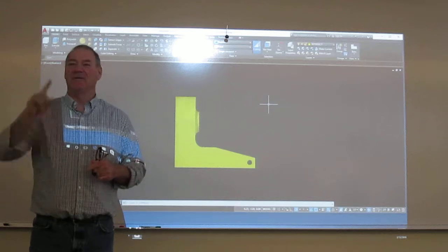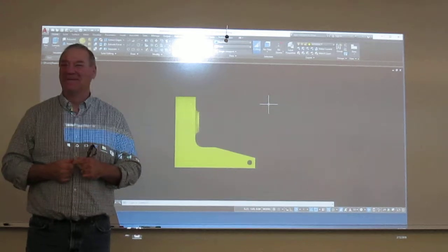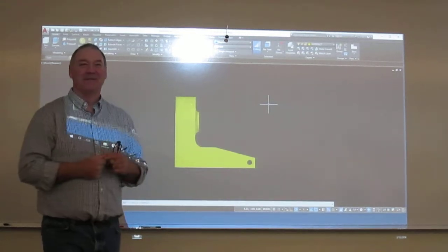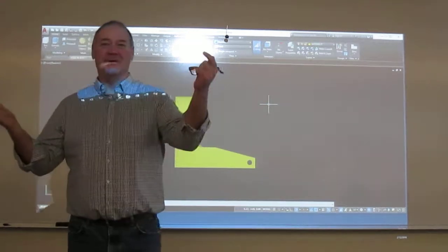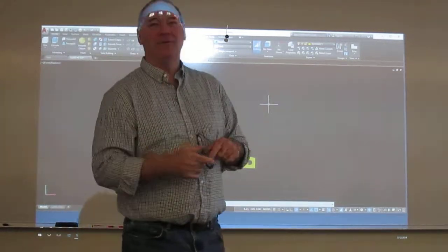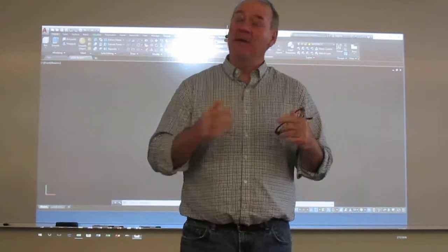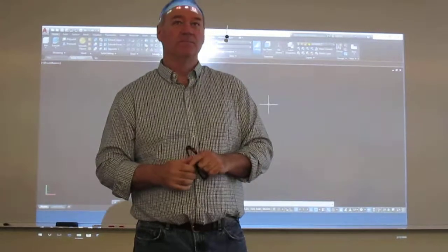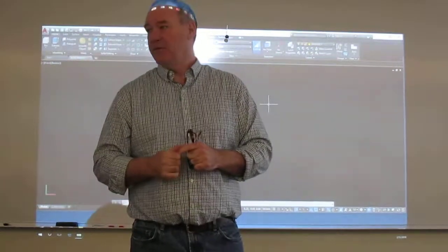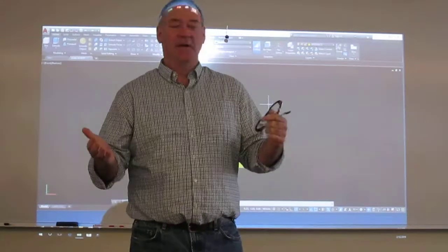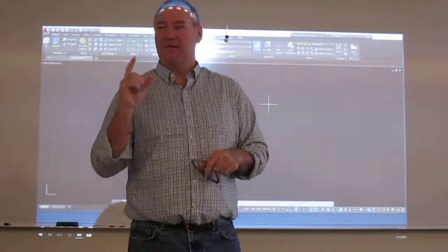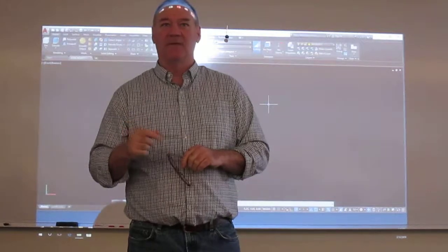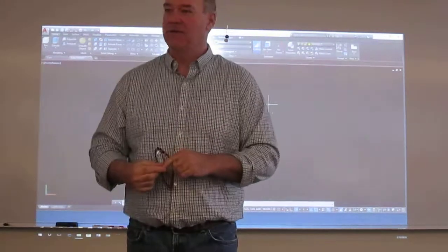Let me ask you, what's probably the first thing you're looking at? The dimensions. Which view you're going to make the front view? Okay, where's my front view? And conversely, what's off of that is how many other views am I doing? Is it a 2-view drawing? Is it a 3-view drawing? Us as drafters, that's the first thing we do, a shape description, isn't it? Because we have to completely describe the geometry.